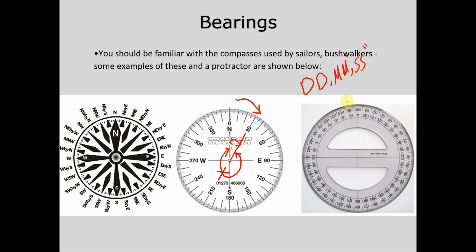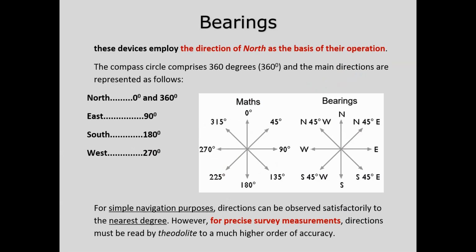There we go, guys. So you have it. If that's our bearing at north, anything within the first quadrant, the first quarter of that circle, will be between 0 and 90. So if I describe any bearing angle between 0 and 90, the minute I say the bearing angle is, let's say, 65 degrees, 30 minutes and 10 seconds, I should straight away imagine a line starting from here and moving there.